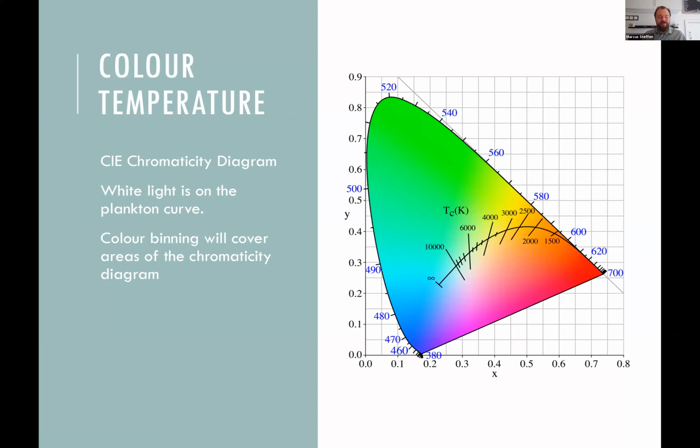Now, the problem is, and this has become much more apparent with LEDs now, is that you get huge variations in what is produced. Even in the manufacturing process, it's not an accurate process when you go and make LEDs. It's not like you choose to make exactly the same thing over and over. When they do the coatings, there is variation in those coatings. So what can happen is the LED chip manufacturer will produce a huge number of LEDs, and there'll be a whole range of different whites available. And so what they do is they split those down into bins and they group them, matching those colors.